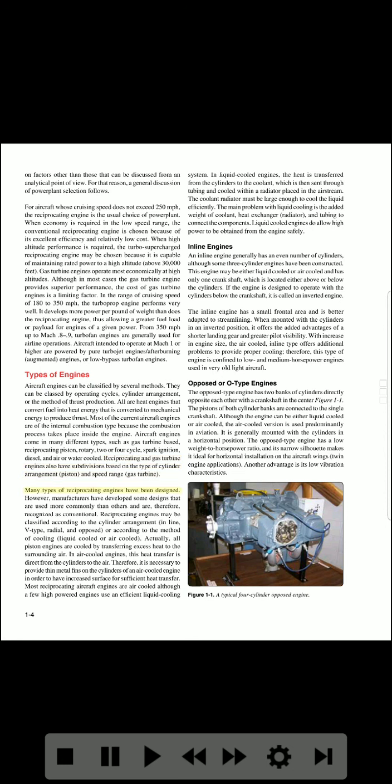Reciprocating engines. Many types of reciprocating engines have been designed. However, manufacturers have developed some designs that are used more commonly than others and are, therefore, recognized as conventional. Reciprocating engines may be classified according to the cylinder arrangement, inline, V-type, radial, and opposed, or according to the method of cooling, liquid-cooled or air-cooled. Actually, all piston engines are cooled by transferring excess heat to the surrounding air. In air-cooled engines, this heat transfer is direct from the cylinders to the air. Therefore, it is necessary to provide thin metal fins on the cylinders of an air-cooled engine in order to have increased surface for sufficient heat transfer.